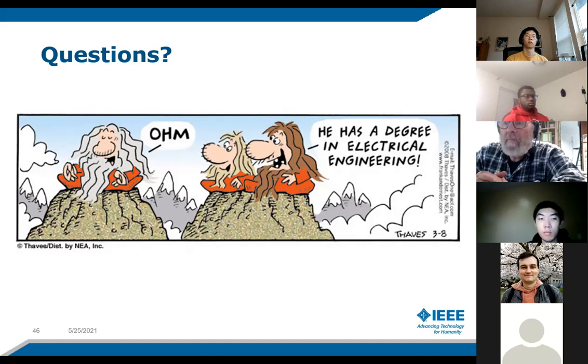So does Bluetooth tethering use Bluetooth 5.0, or is it the classic, or you don't know? I'd have to read the specs from the manufacturer, but I'm guessing that it can use low energy to find other devices, and depending on the data rates, it might cut back to Bluetooth EDR if it's trying to deliver, let's say, 3 megabits per second.